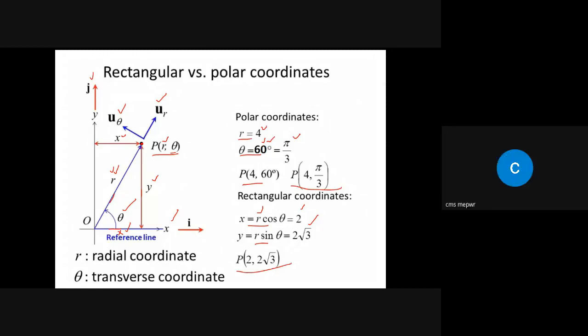So you can make the same diagram with the help of the Cartesian coordinate system. For example, if you want to draw this line, it is very easy using Cartesian coordinates. Then if you want to draw this line and again this line, and you are given this angle and this dimension, from here till this point it is very easy to draw with Cartesian coordinates. Then from here till this point, you can do it by using Cartesian coordinates, but the easiest way is by using polar coordinates. If this angle is 30, you just take R equal to 2 and angle equal to 30, and you will get this point.